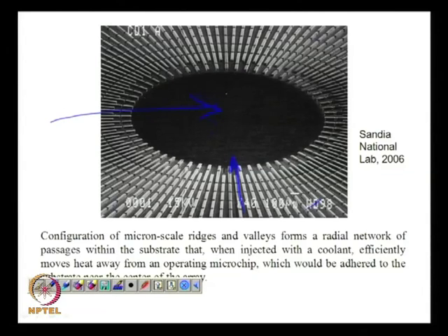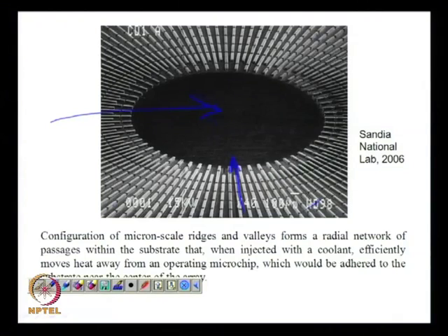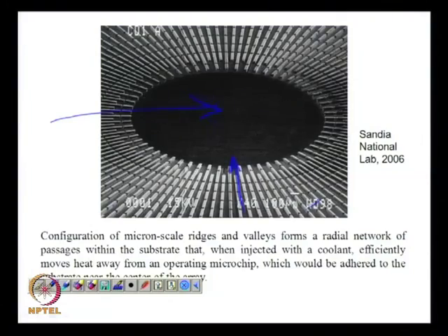And another silicon wafer would be bonded on top of this. That will not be grooved, so it is going to create the closure for these grooves, and through the grooves the liquid will flow, and some portion of the groove will be utilized for return of the vapor towards the cooler section. So, this is how the entire process will keep on extracting heat from the center towards the periphery.